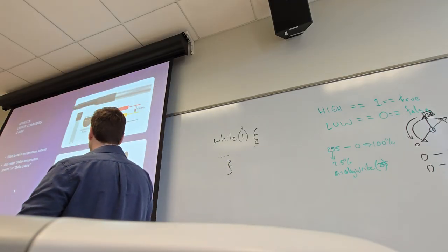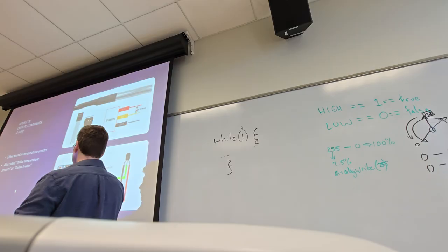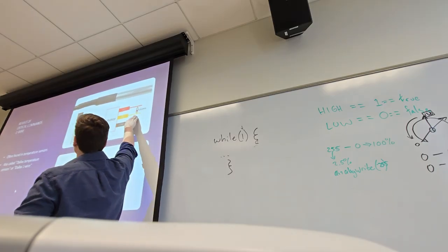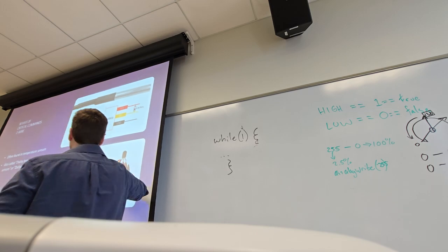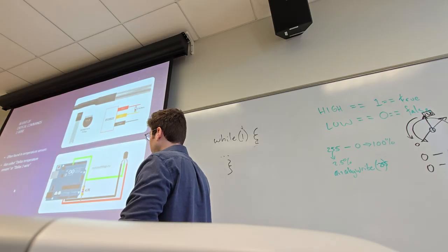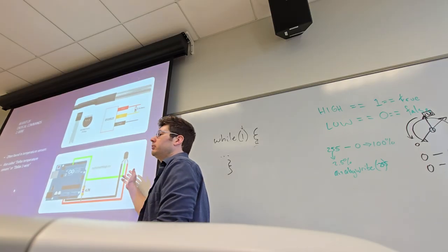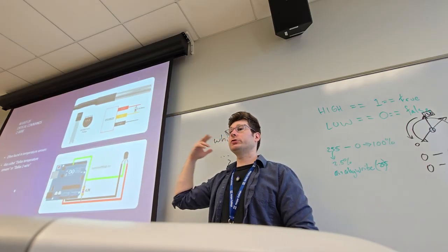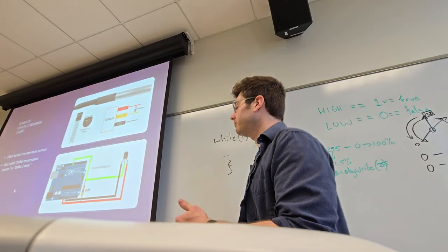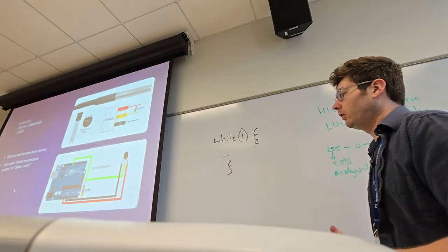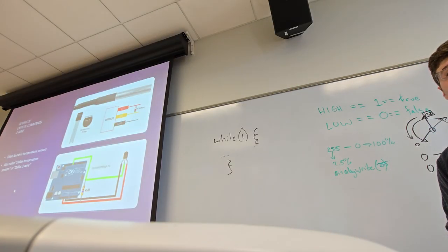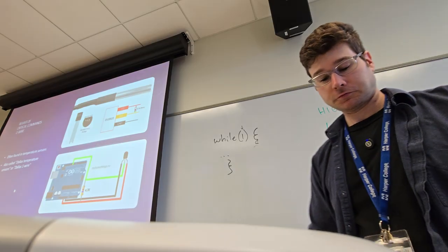Aside from that, these almost always need a pull-up resistor added to them. So if you try to use one of these in the future and don't know why it's not working, it's because you don't have a pull-up on it. They are otherwise extremely easy to use, okay? Again, it'll have a library for it, where you can call sensor.temperature and get back a human readable temperature in Celsius down to the 10th of a degree. Okay, they're cheap and effective. You just got to know how to work with them, how to connect them, and how to write software for them. And it's easier than you think, I think.